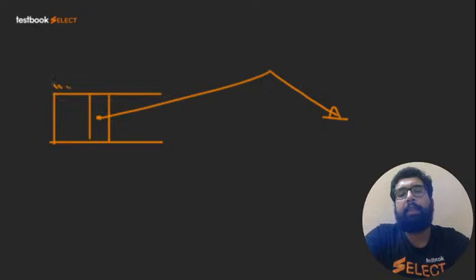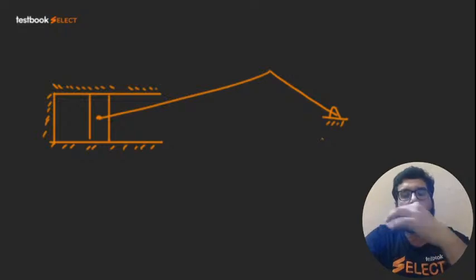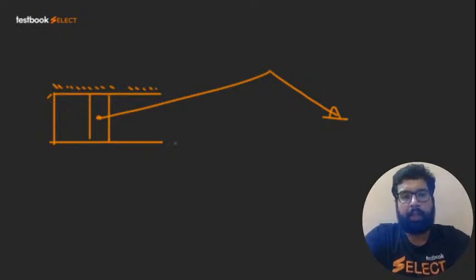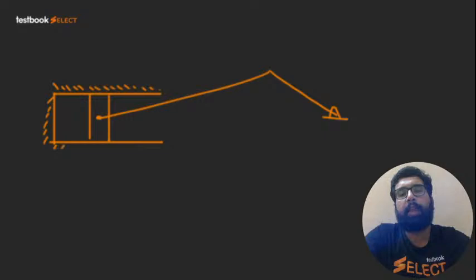Now, beta, unless I fix something in here, like if I do not fix the cylinder, this is of no use. Without fixing it, it was a chain because the first link was connected to the last link, right? In this we can say without fixing anything, it was a chain. But to have some use of it, we need to fix one link. At least one link is to be fixed. Only one link at a time is going to get fixed.